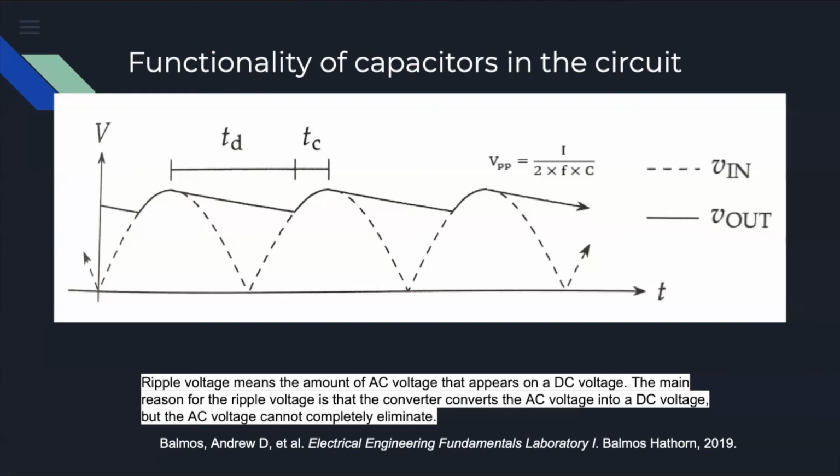Apart from this, following are equally important functions of a filter capacitor. Number one, it improves transient current response. The larger the capacitor, the better it will cater to the transient demands of the load. Transient current is current spikes. It improves voltage regulation of the power supply.